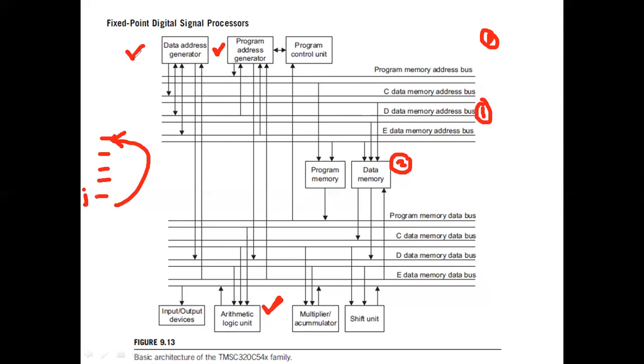The same is the case with data also. If you're using pointers and incrementing pointers, where actually is your data? To control the direction of the program, you use the program address generator, exclusive, other than your conventional ALU. And then for generating the actual data pointers, you use the data address generator. So this was the third very, very staggering thing that we noticed.